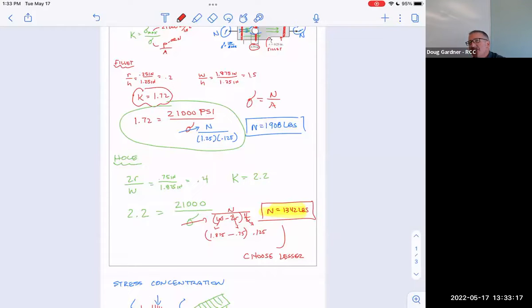And so there was this teeny little bolt on the outside of the motor that was a part of the connection. It was like this female pipe and this male pipe, and then there was a bolt sticking through it, and that was designed in to be the weakest link. So if it hits something, it would shear that bolt off. 20 cents. I have like 3 of them in my pocket when I'm driving that thing. Just go out there, line it back up, put another one in, and take off again. Motor's not broke, tractor's not broke.